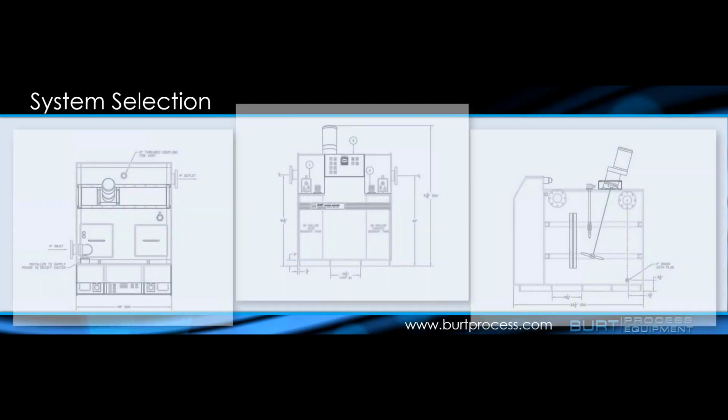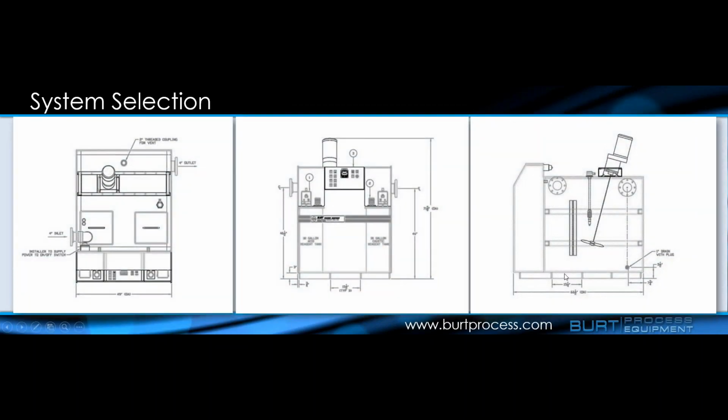This is what a PHX looks like from a drawing standpoint. This is your top view. You have your access manways. That's your downpipe, chemical injections like a standard pH system, vent connection, mixer. From the front, this is your control console. Here, you have your metering pumps, low level switches. Behind this panel here are your reagent tanks, which are 110% double contained. Same thing for your caustic side here. Looking at the inside, again, this is your reagent injections going in, pH probe, there's your agitator, and there's your effluents, as well as your power disconnect switch.